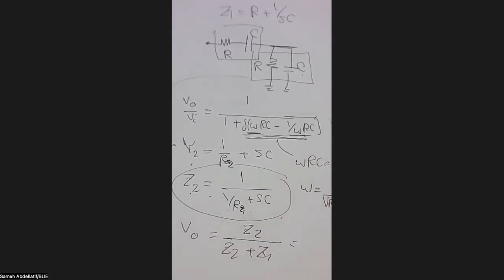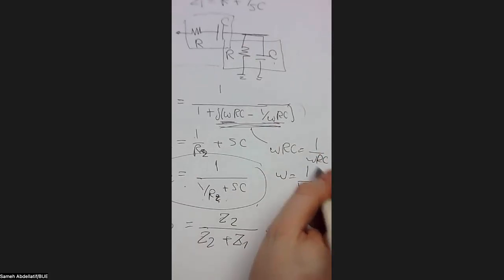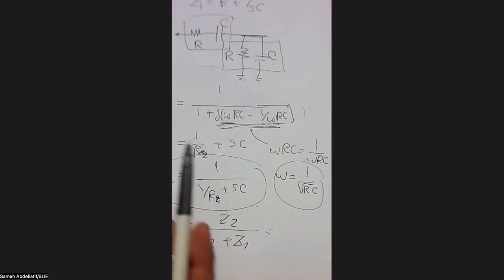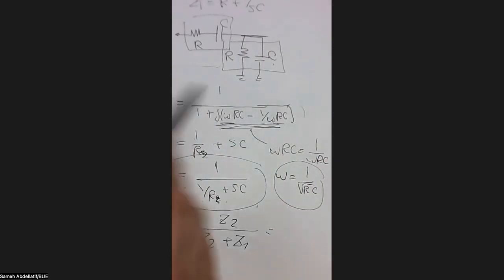Having the same frequency selection network with an amplification network which is frequency independent, as in our case, simply means that you are not going to change the oscillating frequency. Typically, as you can see here, the oscillating frequency is a frequency dependent parameter, depending on the omegas, which generally appear whenever you have a capacitive or inductive part.